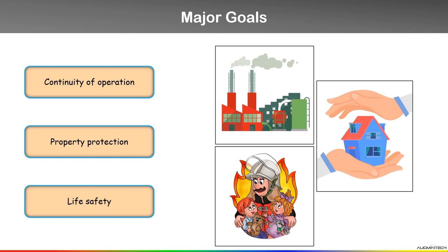Do not ever take the elevator, and wet all the walls, doors and windows, and keep a wet cloth over your nose and mouth, because in a fire we have smoke, and smoke travels at a speed of 120 to 420 fpm. Smoke generally enters our nose, so we have to keep a wet cloth over our nose and mouth, because smoke contains very harmful and toxic gases. So these are the three main goals of using a firefighting system.